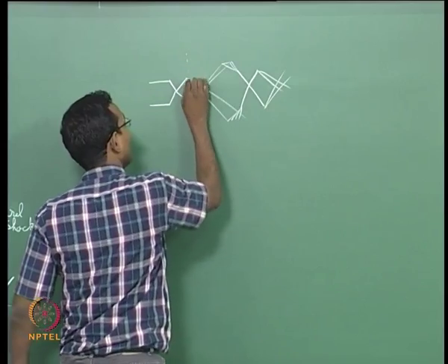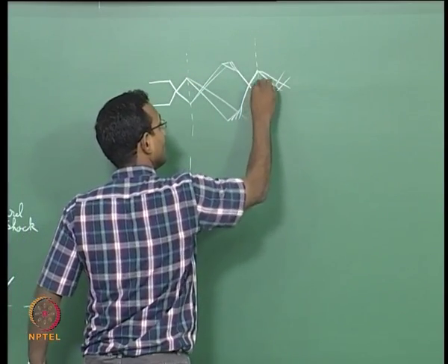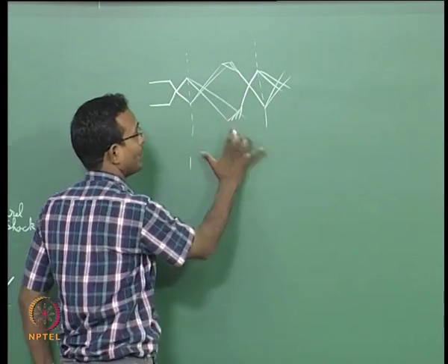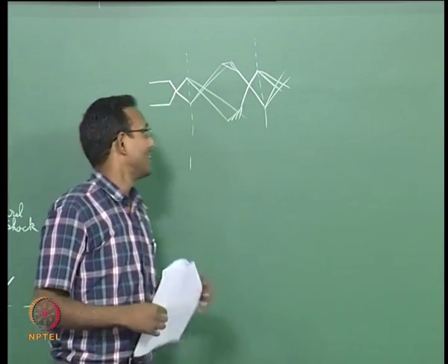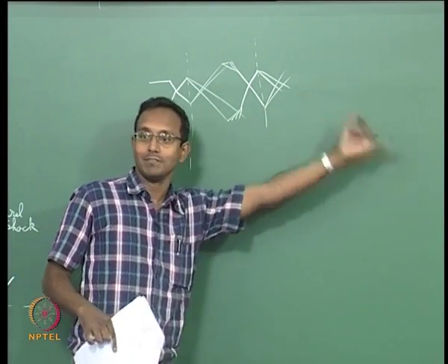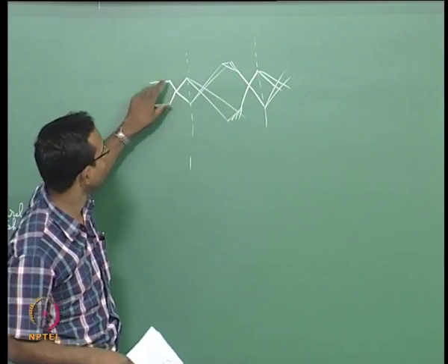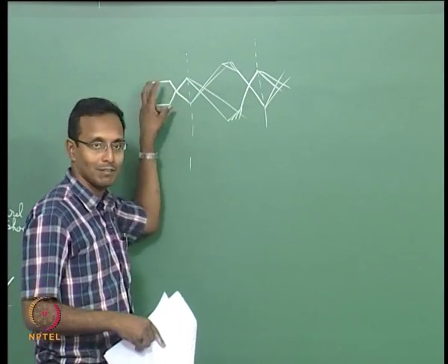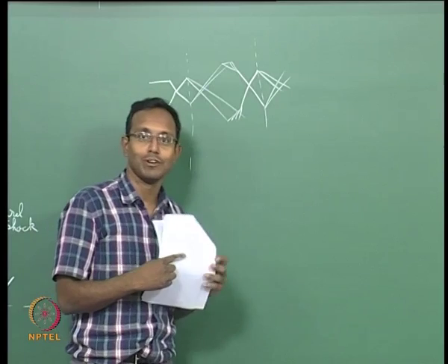If you look at it, the only thing that repeats will be from here to here. This whole structure can be put one more level here and one more level here and one more like this. It is always the expansion compression structure that is going to be repeated several times. Only difference in an over expanded jet is it will have this initial portion of some two shocks crossing. After that it forms the other structure and it just goes on like this forever.